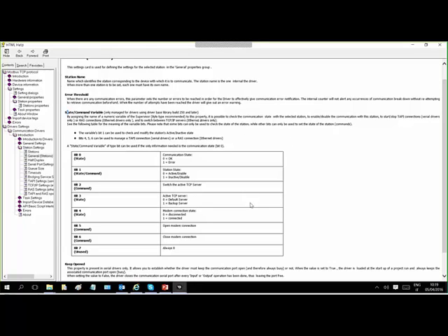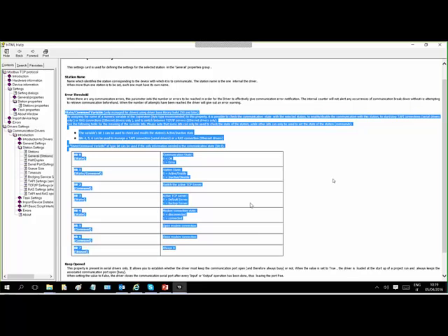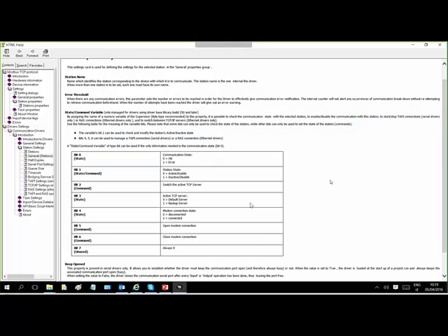The state command variable is really important because it allows you to insert a variable, a byte, and through this variable you can retrieve very important information, like the communication state. So the first bit of this byte says that if it's 0, communication is okay. If you go in error, you have a communication error specific to this station. You can generate an alarm message in your window. You can gray out the screen interface for the operator to alert that you lose the communication. You can do your action based on this bit of the state command variable.